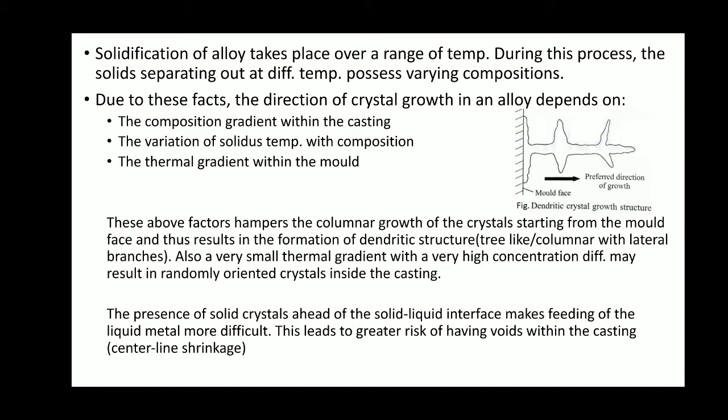The dendritic structure develops during the solidification process, and as the whole solidification happens within a temperature range, at a certain time we have grains which are solid, and these dendritic structures entrap certain liquid islands or liquid regions, so we get a mushy zone. We also said that a solid-liquid interface, or solidification front, develops in the solidification of alloys.